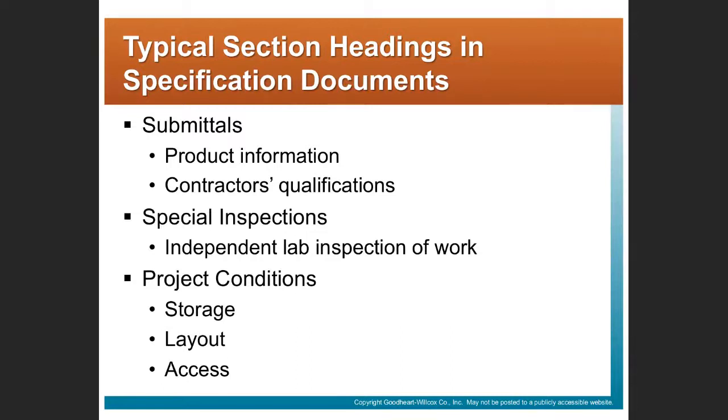There might be special inspections, pressure testing of piping, pressure testing of ductwork. If you're the person pouring the foundation, you probably have to save a sample of your concrete that's subject to testing, to make sure that the concrete you actually use meets the compressive strength requirements in the specification. Those are all things that might be contained in the specifications.